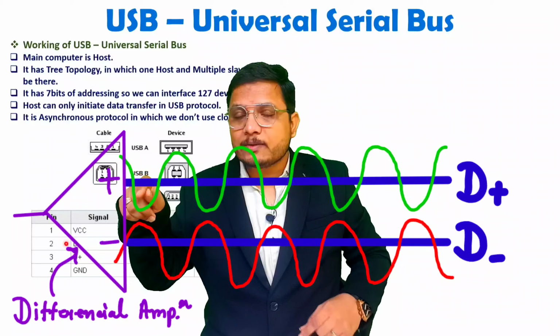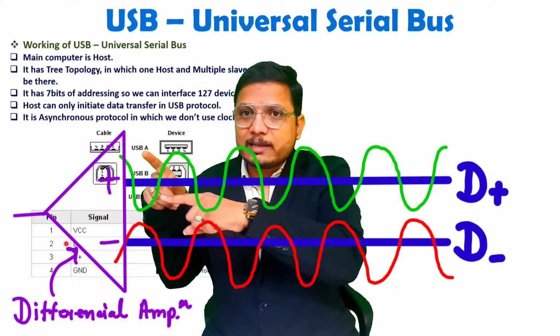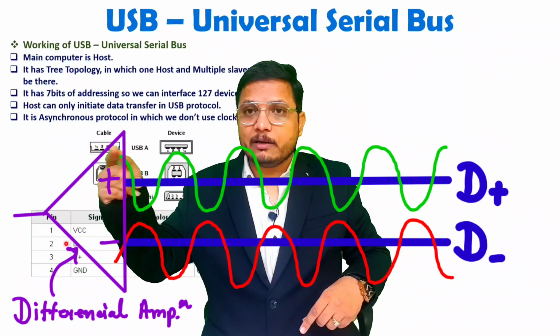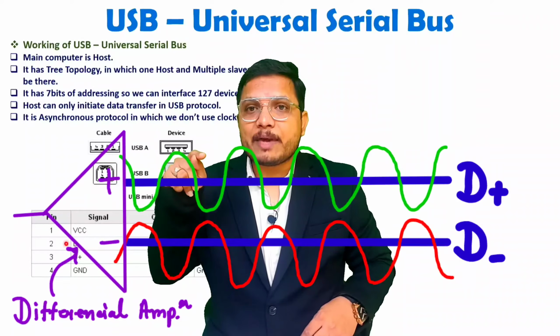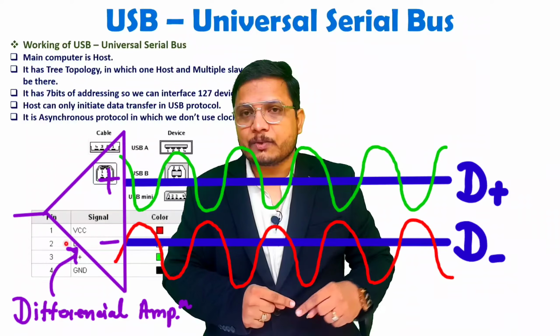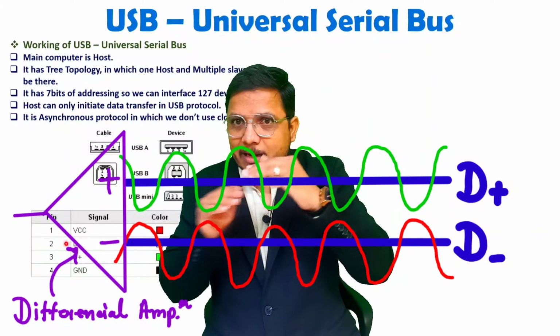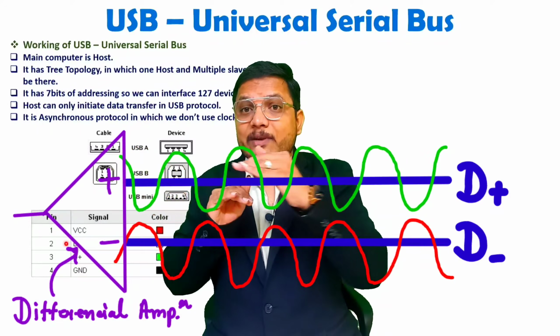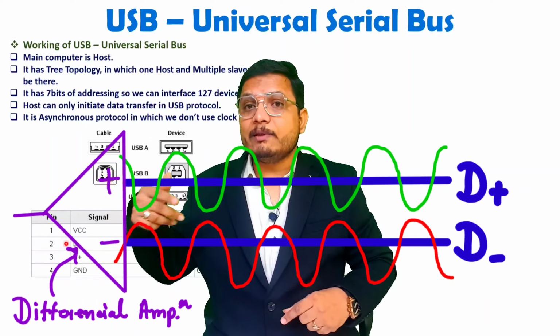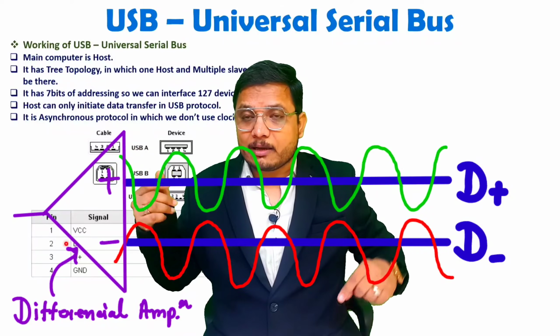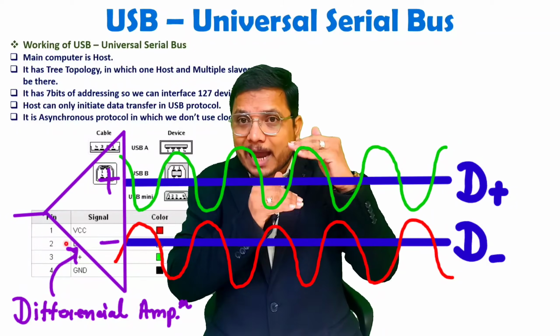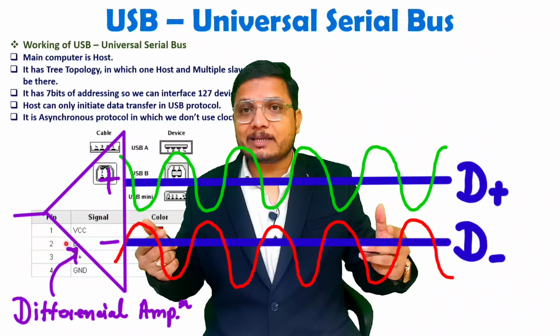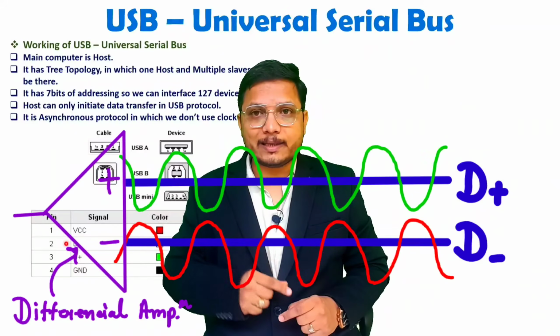So what we do is we take the difference of these 2 signals and then we amplify it. So what will happen? Here you will be having better signal to noise ratio. Same information will be there. Here at the receiver we will be differencing that and amplifying it. With mirror images, that difference will be even larger. That's why you will be having higher SNR.